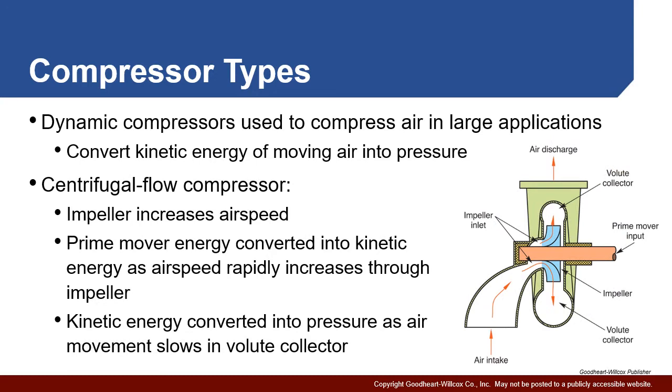Now let's go back to discuss non-positive displacement compressors, or what we refer to as dynamic compressors. Generally, these are going to be used in any application where you want a lot of air movement, but you're not looking for particularly high pressures. The way they work is they speed the air up to give it kinetic energy, and that kinetic energy is then converted to potential energy in the form of pressurized fluid, or compressed air in our case.